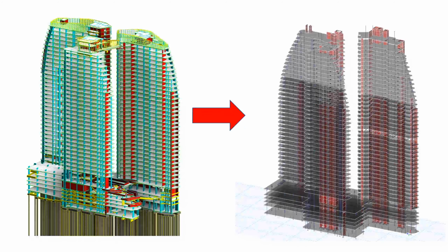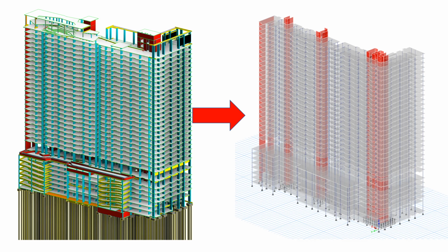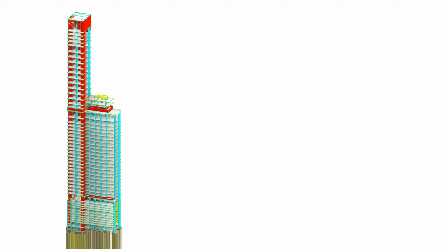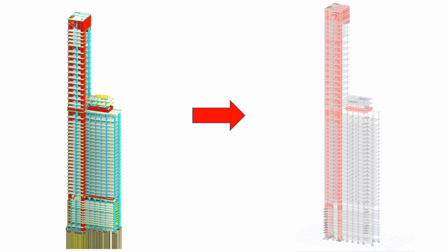And Revit is a great tool for structural engineers to prepare not only the design intent but also a finite element model at the same time. So from now on, when I refer to a finite element model, it will refer to the model composed of line or shell elements. Although Revit is a great tool for making a building model, it does not mean that randomly making a Revit model, which visually looks like a building, will automatically translate to a usable finite element model.